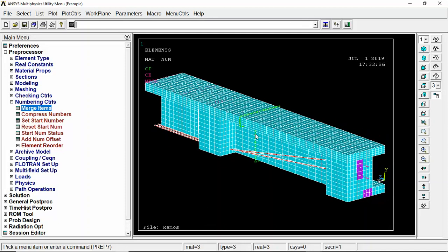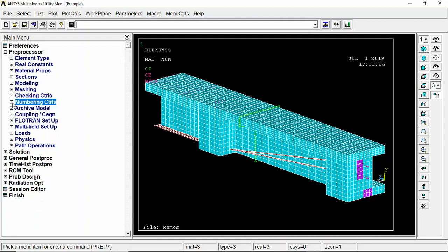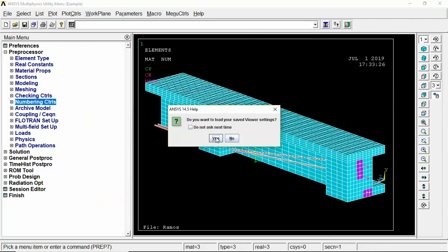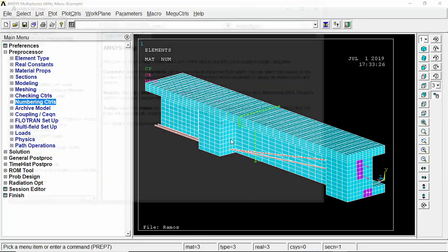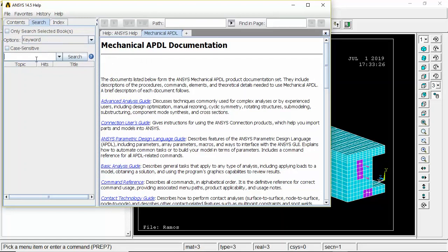In this part I'm going to move to applying the prestress force on the steel. Again you have 3 options to apply the prestress force on your steel. The first and second options are somehow the same. There is a command here called INSTATE. It will apply an initial stress or strain as you want on your structure.